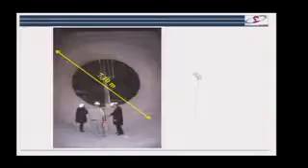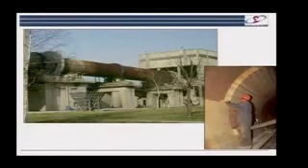There's the kiln. It goes along, and that's me in the cement kiln. It wasn't working at the time, in case you wonder, because it was shut down every year or so. You need to shut down this kiln because it is made of steel, and to protect it from the high temperatures, you have to line it with bricks. These bricks typically last 6 months, a year or so, and then you have to replace the whole thing.